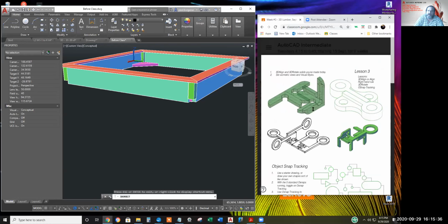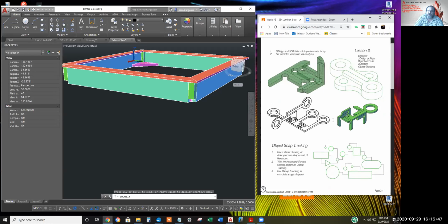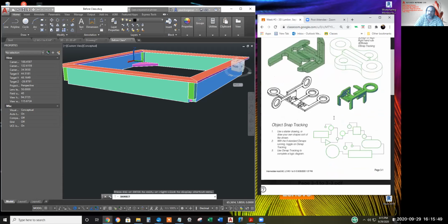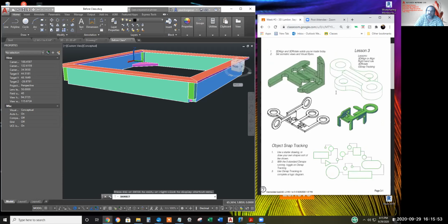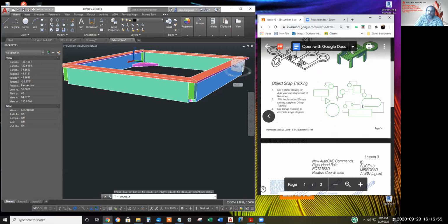We've already aligned those little triangle, pentagon, and hexagons last week, and it's the exact same procedure to align 3D models. You just pick the 3 points to align one with the other. So there's little to gain by this top half. I'll probably take it out, but I would like to cover this object snap tracking.